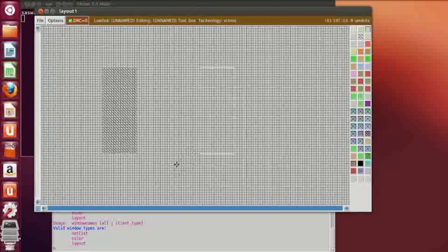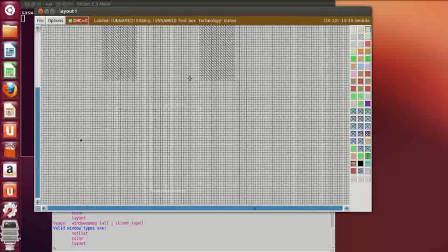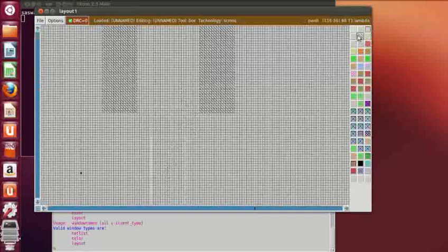Since this is an AND-OR-invert, the AND means the NMOS is in series and the PMOS will be in parallel. So this is one PMOS, this is another PMOS. So middle click on the n-well, and the third PMOS will be in series with these two PMOS. This is A, this is B, this is A dot B, this part is A dot B plus C. So when there's a plus operator or an OR operation, we'll use a series PMOS. So middle click on n-well.